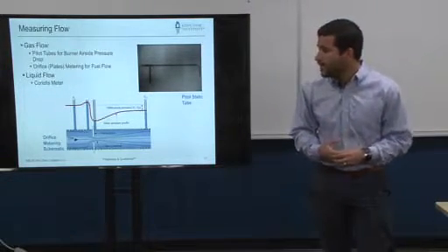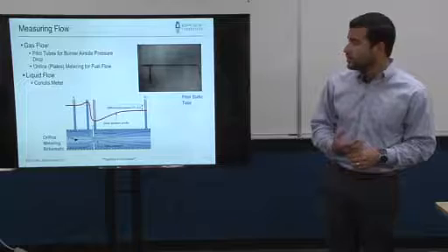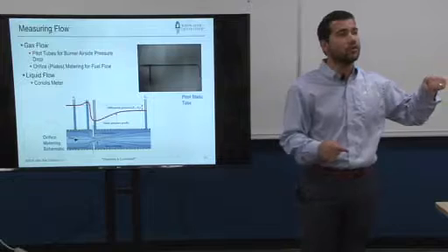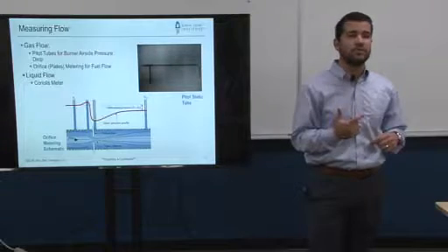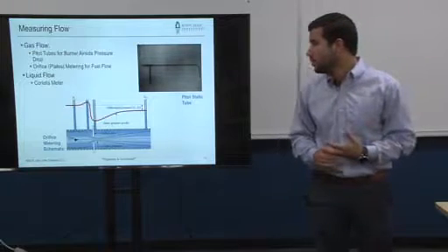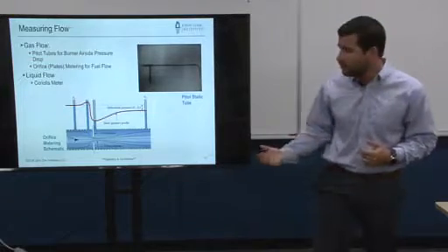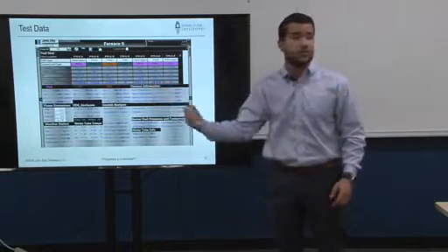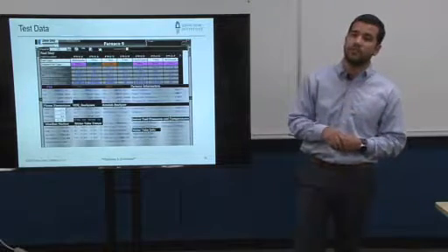Okay, and we use a similar concept for measuring the fuel flow. We just use orifice meters, and in the orifice meter you will have a pressure transmitter right before that drop, and then a pressure transmitter after it. And that difference in pressure, along with a little bit more information like temperatures, pressures, and the actual fuel composition, would tell you how much flow is going through that particular line. So you will have one of those on every single one of those lines. That's exactly how you know the volumetric flow through every single one of the fuel lines there.